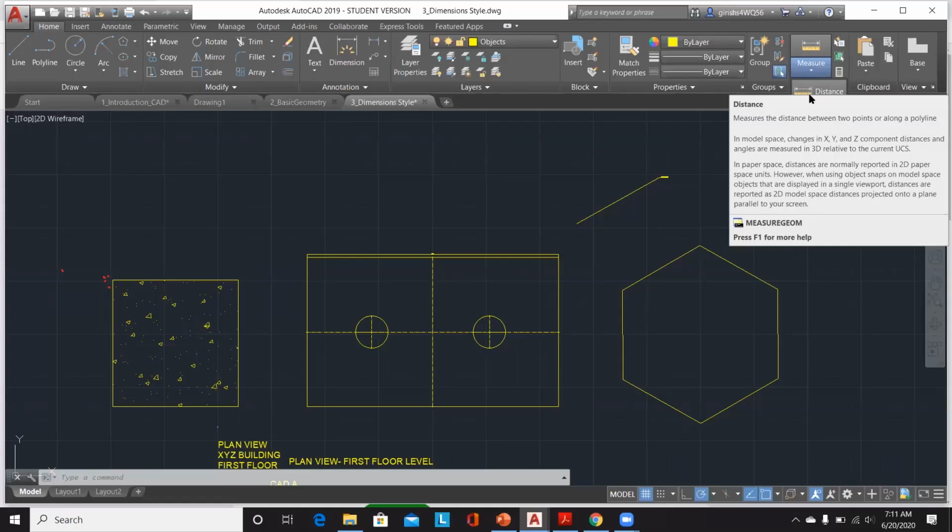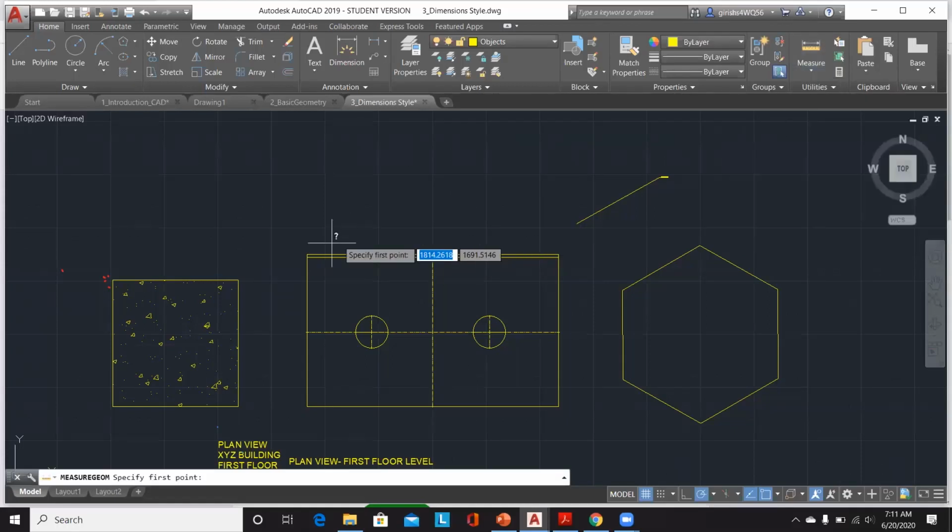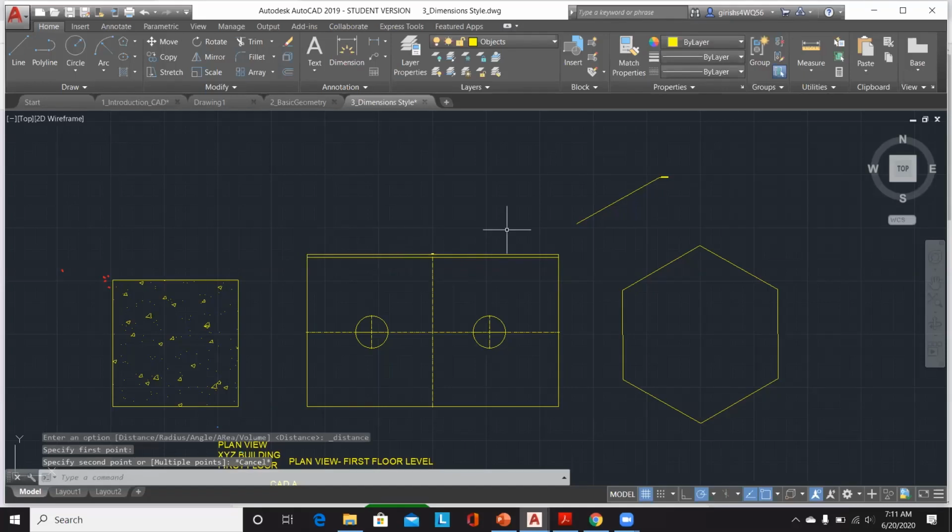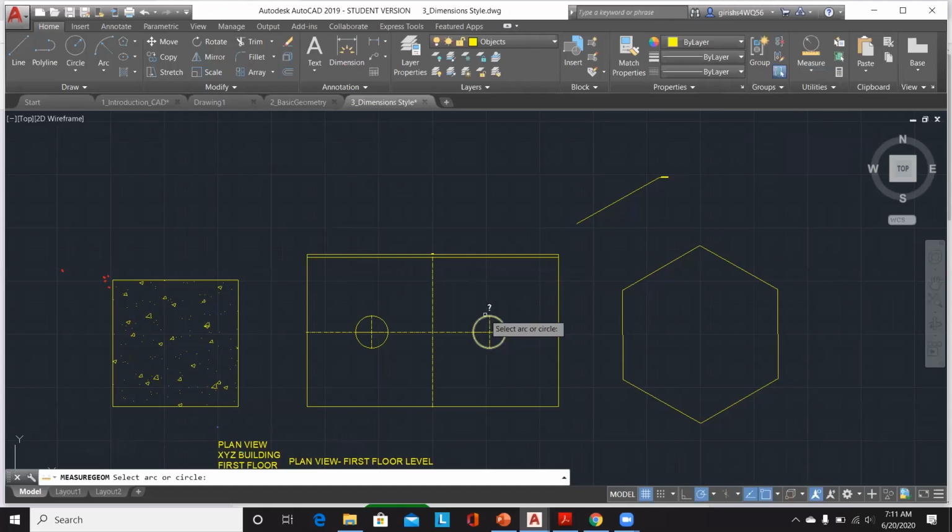You can use the distance tool to measure the distance between lines instead of adding annotation. If you're not happy with your length or line segment, you can modify your measurements, and this is clearly visible compared to annotation, where you have to play trial and error to make it visible in the view settings you need.